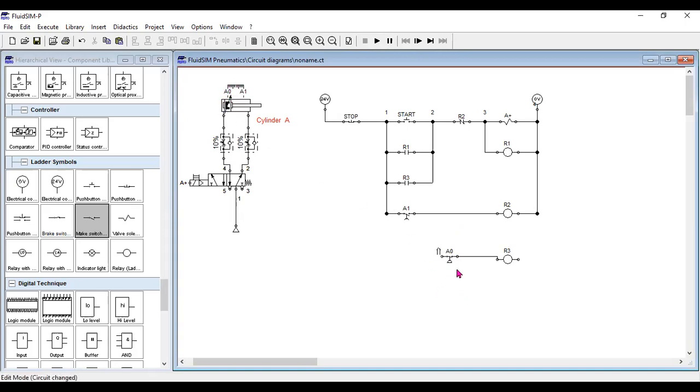If you encounter situations like this, particularly the sensor that detects the retracted status of the cylinder, the secret of the design is not to connect AO directly to the positive terminal, just like this one. Do not connect it, because it will energize the series connected element.